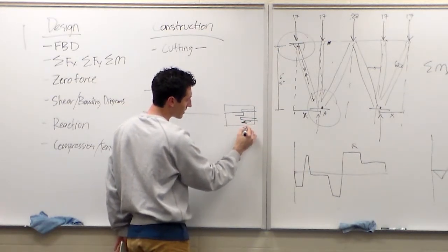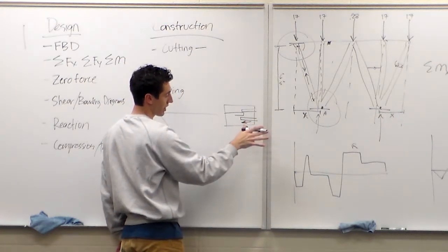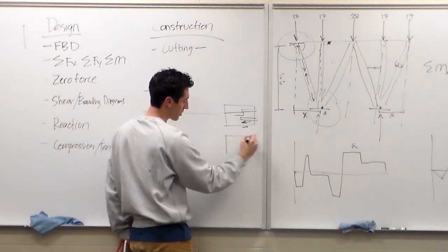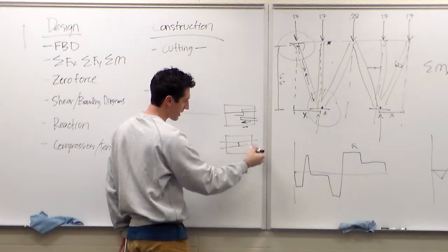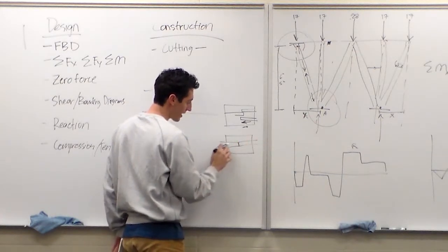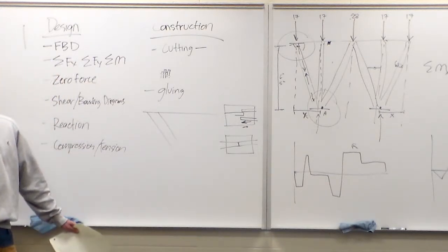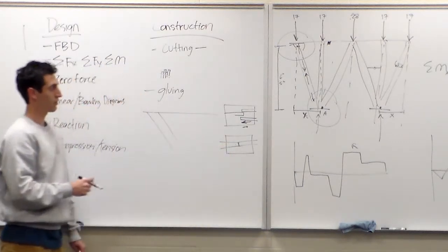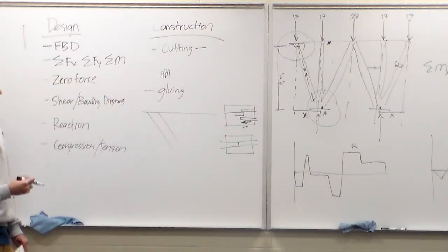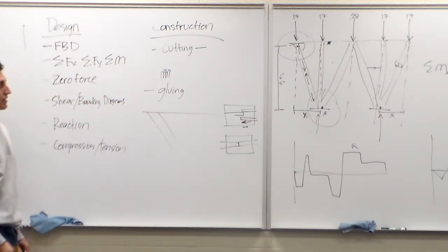All that's holding it is the glue friction pushing that X direction back. If you can line up your beams like that, then you have the force pushing this way and that way, and glue is no longer essential. Actually, it's still important, but it's not the only thing holding these two together. So don't be too creative in building this. It's pretty straightforward, just logic and thinking that the sum of the forces needs to equal 0.